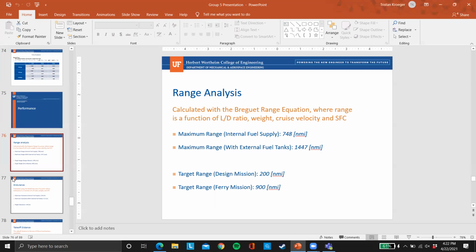So here is what I want to say. The place that you put the payload, let's say weapon, you cannot just simply put a fuel tank there, because a fuel tank is not just a simple fuel tank. There are fuel tank feed systems. You need to consider how the fuel in the fuel tank gets into the engine, to be actually used by the engine.